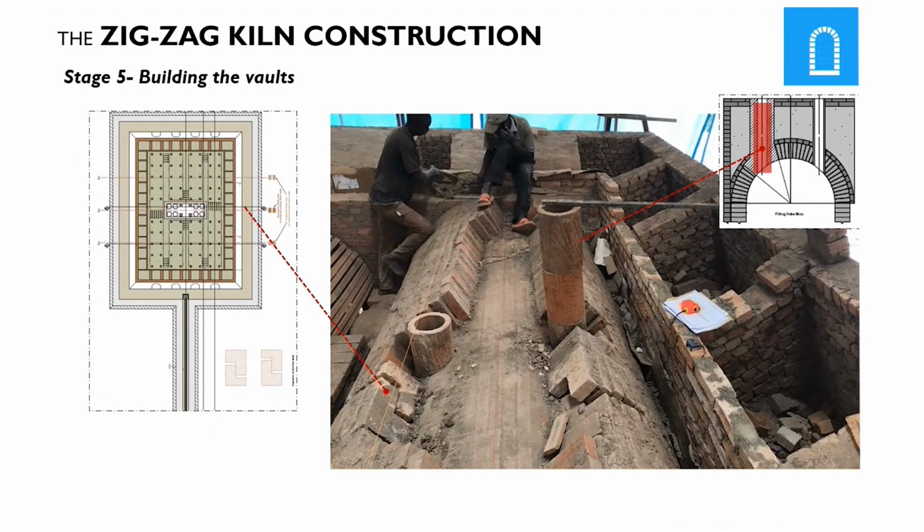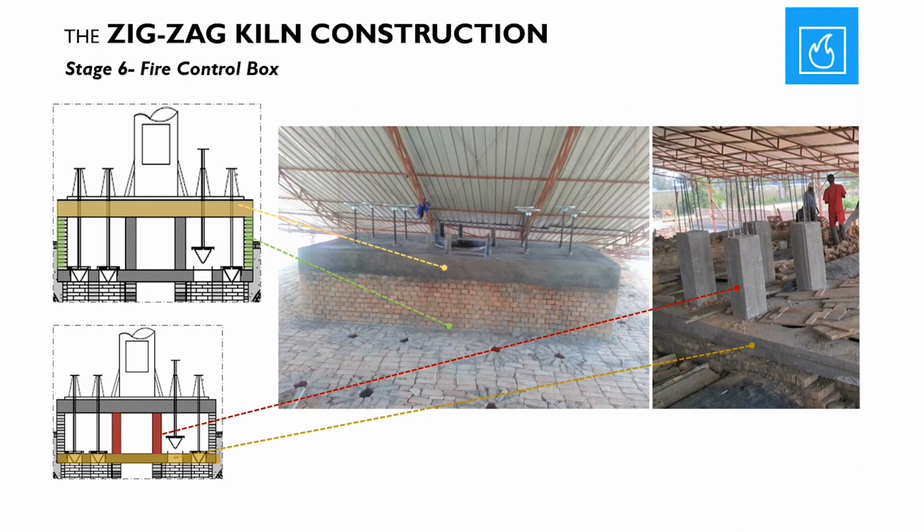Before ending stage 5, note that special L-shaped bricks are used to make expansion joints, which are placed in designated places. There is an expansion joint at each position of the kiln. Expansion joints in the vaults are sealed with fire-resistant material such as kaolin. Fuel-feeding bricks are inserted in place, creating the holes for feeding the firing fuel.